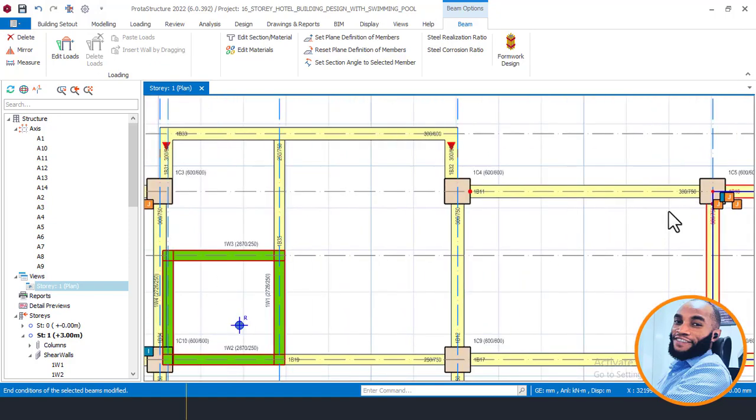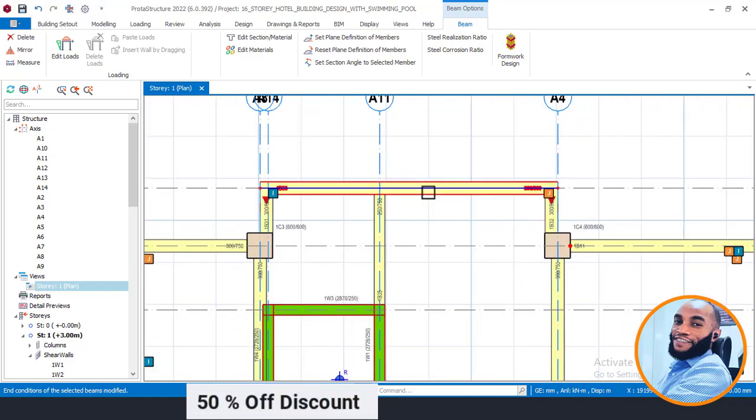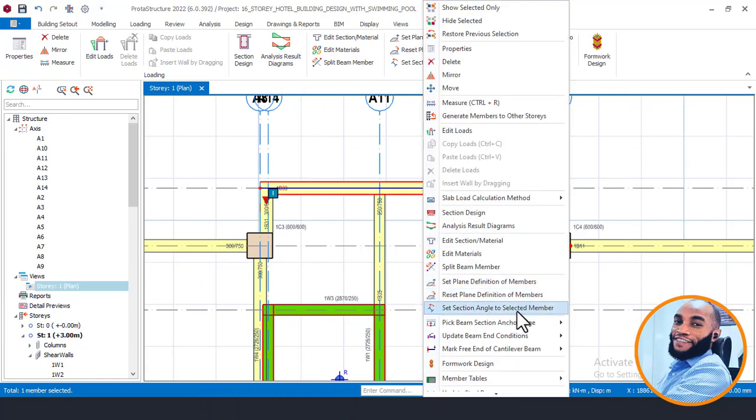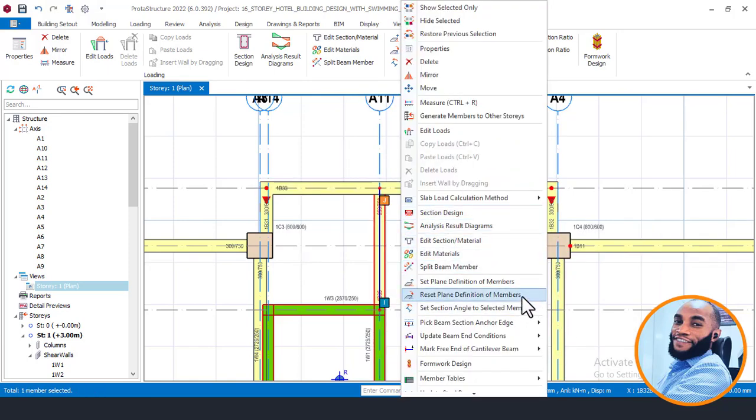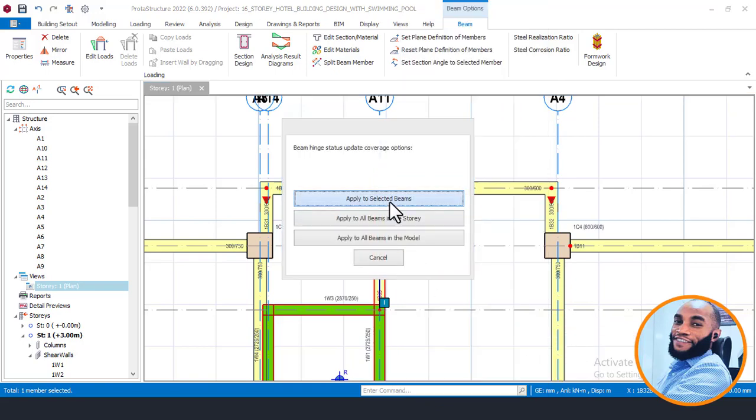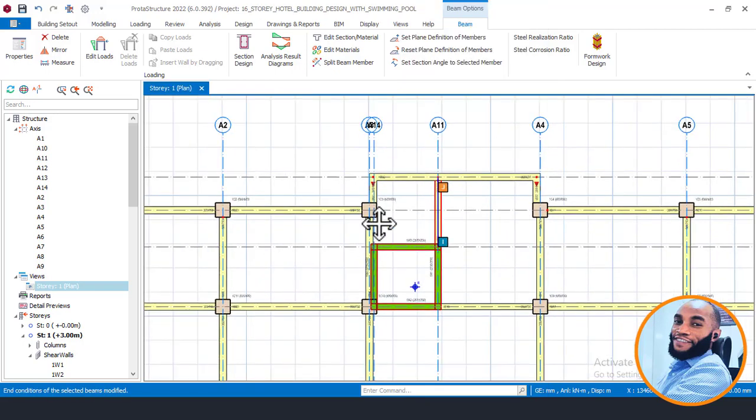And I'll now come and hinge the what? Single selected beam, which is this one here. Come here and hinge what? At both ends here. Okay. And I'll say what's selected here, apply, and I'll come again and hinge both ends. Okay, then come here, both ends. Okay, and then come here. So right now you can see how to release moments.